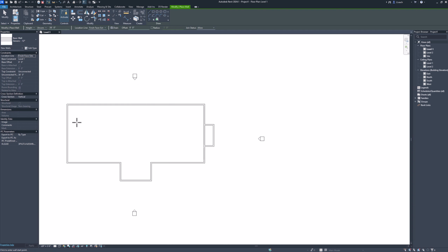Hit the escape key. What I want to do is to go in my clockwise fashion, so I want to start with the bottom here. Draw it over. What did I say that was? 9'4". So straight over 9 space 4. I'm going to go up, go over, hit this. I'm going to go to modify, hit the modify.